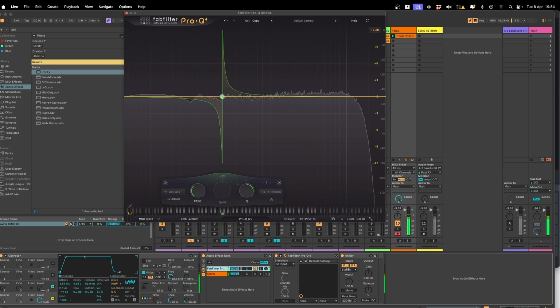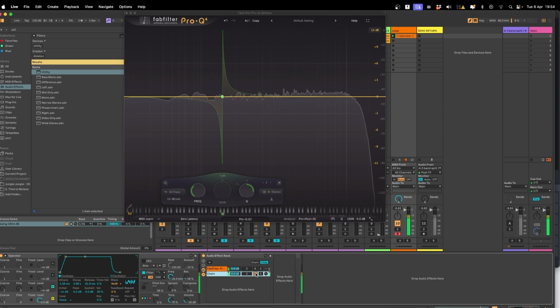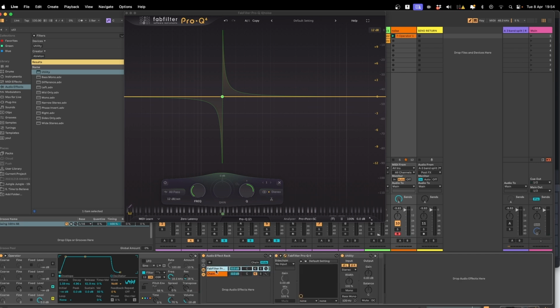Now I'm flipping the polarity of the signal and I'm adding this to the dry signal. So basically what's happening is that everything that is the same between the two signals will get removed. Everything that is the same without the effect of the filter, because it's flipped in polarity, will now be inverted from the dry signal. So they will be subtracting, while everything that has been shifted in phase will remain. Let's listen to that. Oh.